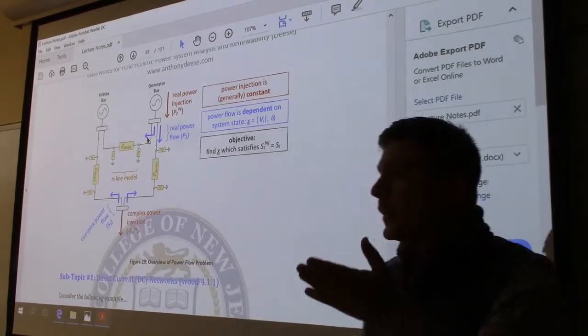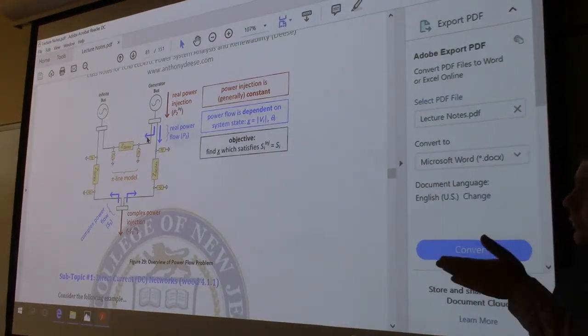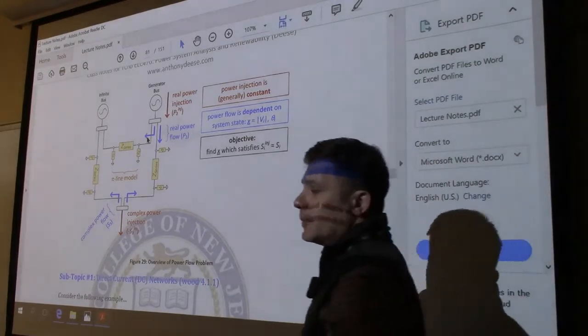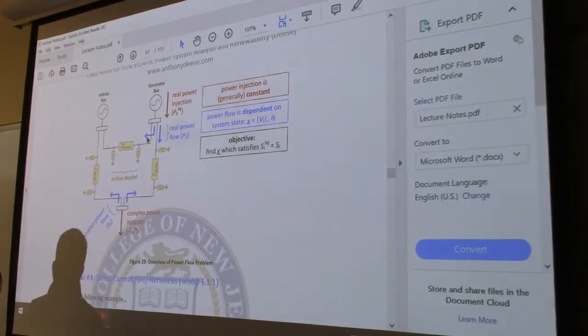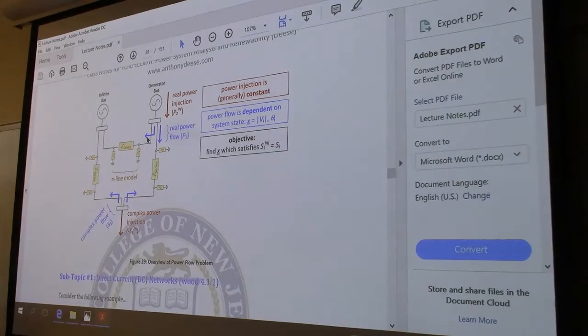And why do we need an infinite bus, period? Why don't we just have 2 PV buses and a PQ bus? The reason why we need an infinite bus is because the problem becomes over-constrained without the infinite bus there, which means that if there is a solution that exists, it will be very hard to find it mathematically. And in most cases, there won't be a viable solution.